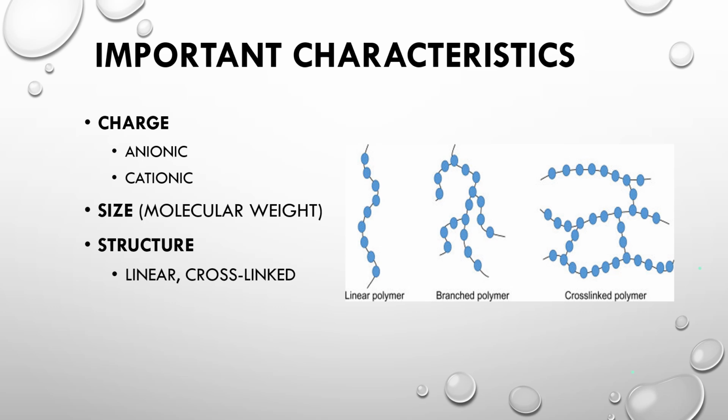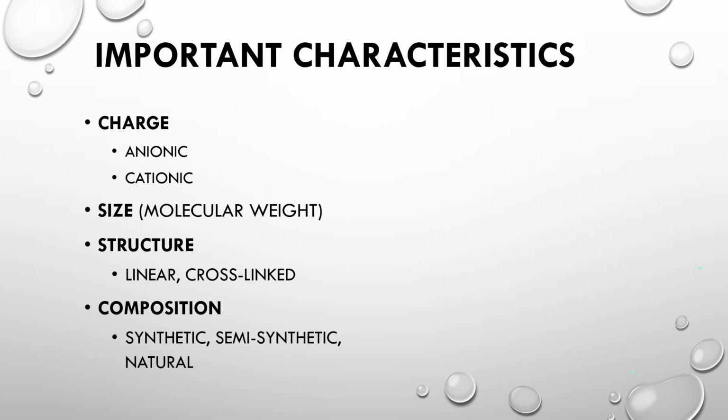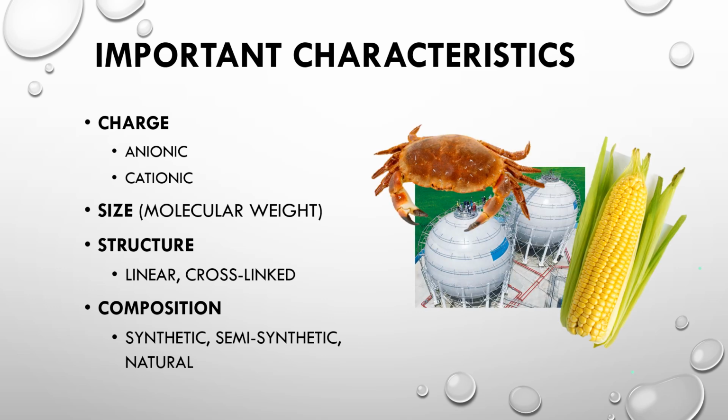So we're using anionic, high molecular weight, linear polymers. And if you look at most states' guidelines, they're going to list those things. Now this is helping us understand why specifically they have those guidelines for the different polymers. Again, they can come in different materials as well. The PAM is an organic molecule that's man-made, it's synthetic. But again, we can make it in any charge or any size, which makes it safe and very effective.